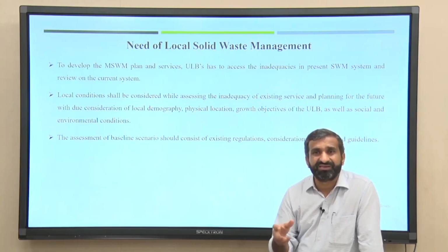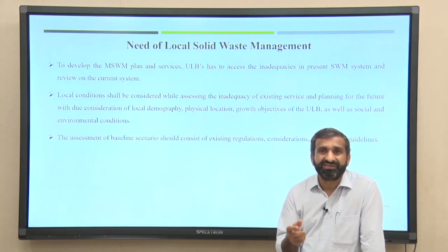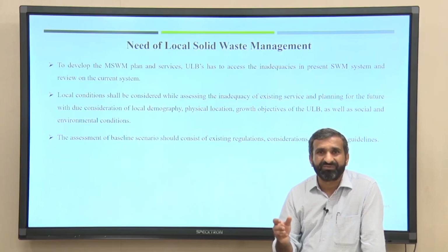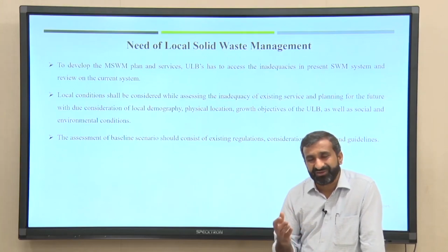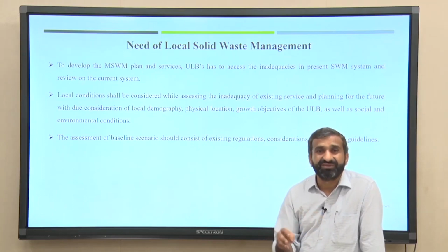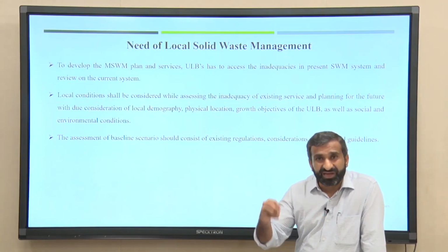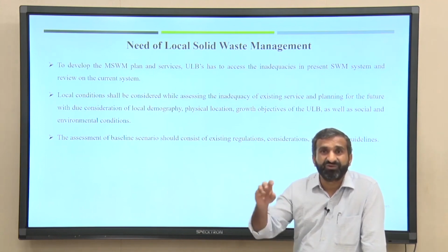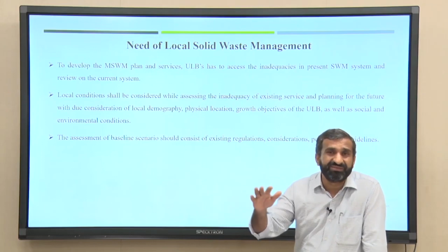No, local conditions say that 8 months of rain means you can't have the landfill. It is very difficult because your groundwater table will be very high. So, it is very difficult to have sanitary landfills in such areas. Even for sanitary landfills, the type of sanitary landfill will be different in hilly regions. We can't go for simple excavation or area methods.